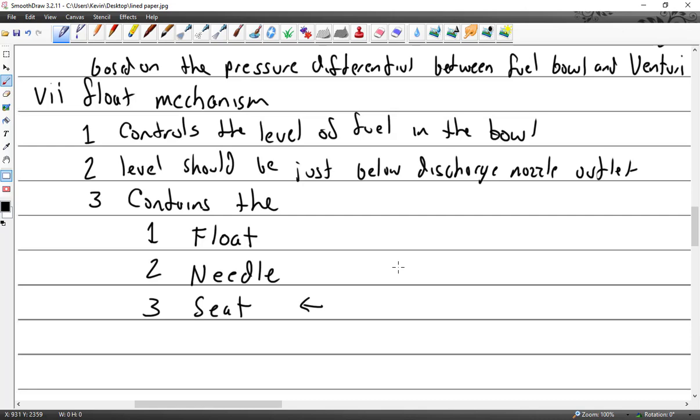How would a person know that we have this problem? How can you identify a leaky carburetor? Look underneath the nose, and there's stains. Now, you won't have a fuel puddle. You'll have blue stains. Aviation fuel does a pretty nice job of evaporating, but the one thing that doesn't evaporate is the blue dye. So you always look for your tattletale blue dyes.